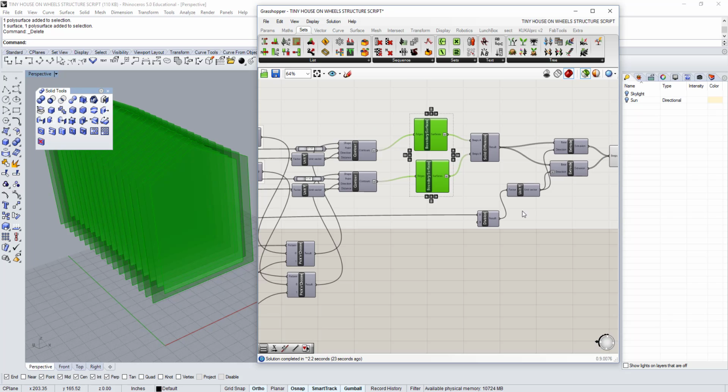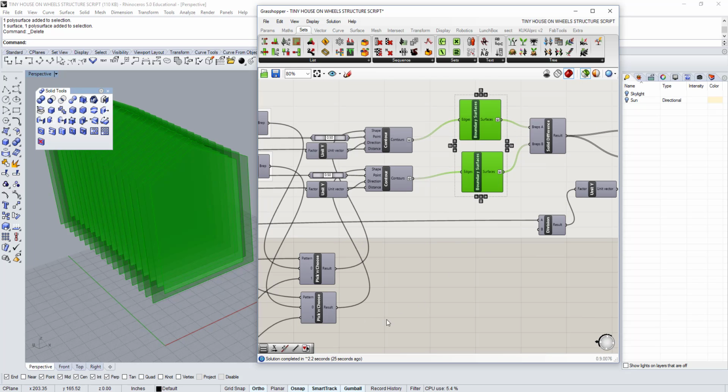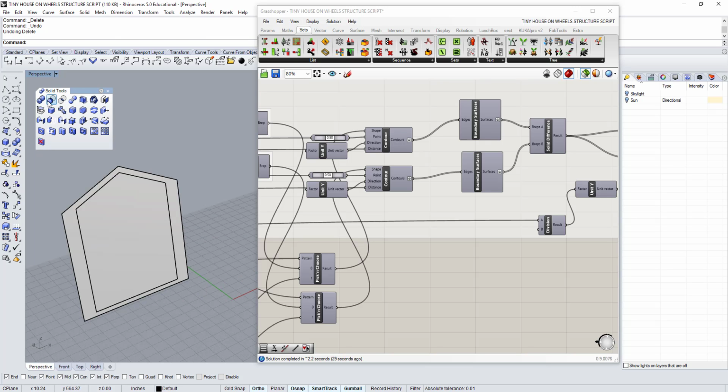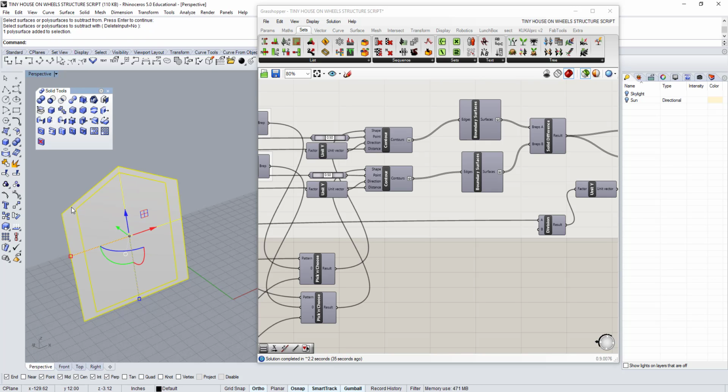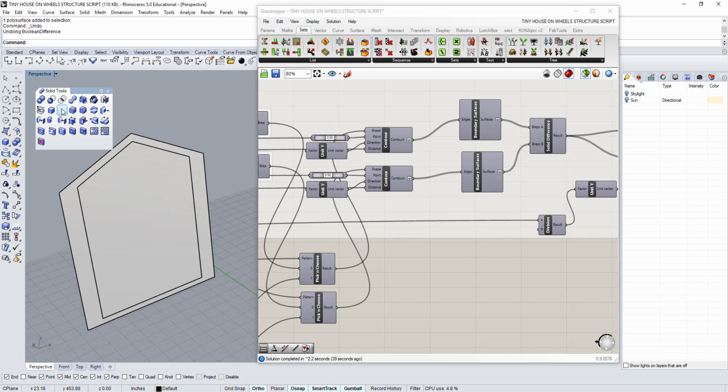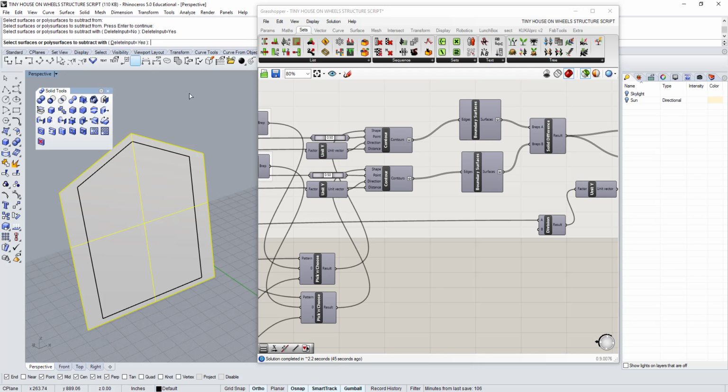so we fixed one problem, but we still have another problem. Actually, let's undo this surface and try to do a solid difference here. So I'm going to do a solid Boolean difference, subtract from this one, delete input, yes, select that one, enter.